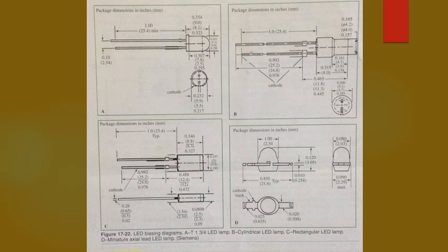Diode characteristics and ratings. Ratings of diodes and rectifiers are commonly based on current and voltage capabilities and peak inverse voltage. The peak inverse voltage, or PIV, rating used by manufacturers defines the greatest reverse voltage that can be applied across a rectifier without damaging it.